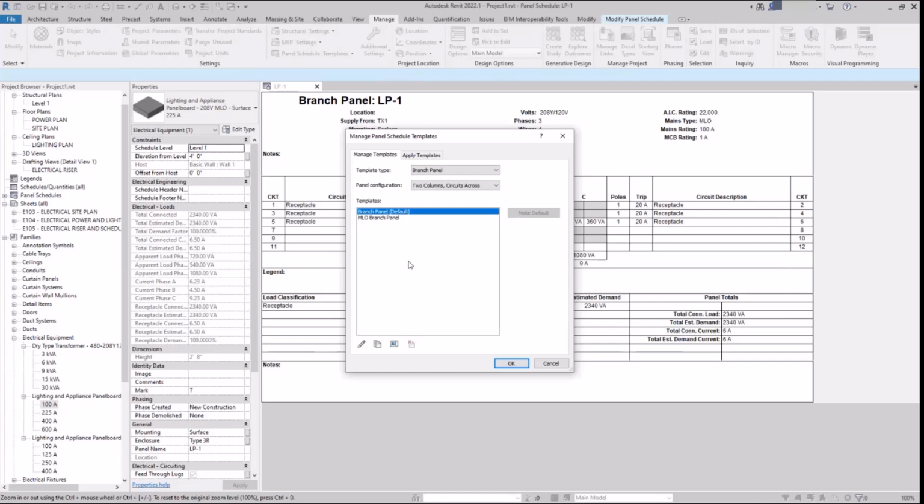Actually, no. That is not an accurate understanding. The panel boards over here do not have panel schedules associated with them. The panel schedules that live here live in the model itself, regardless of what you bring in. Okay. Now, there's a way to do transfer project standards, which means that you can take whatever you've built here and move them to other projects. So that's how you would get panel schedules that you make into other projects.